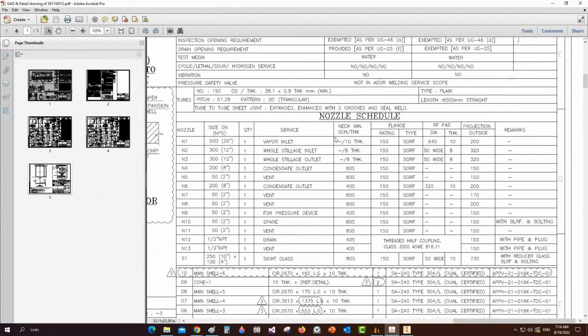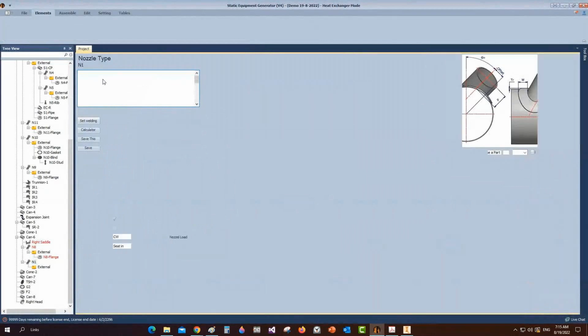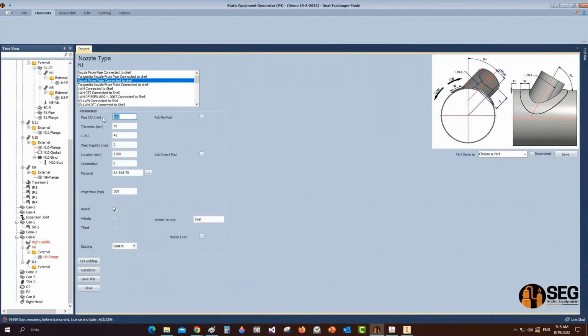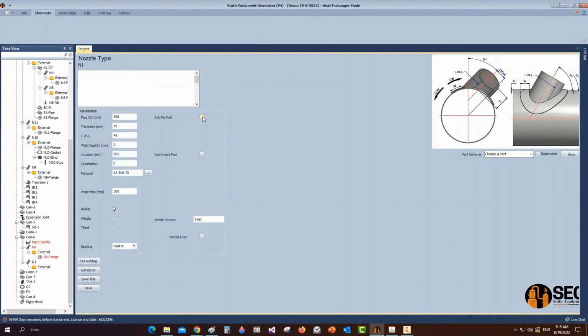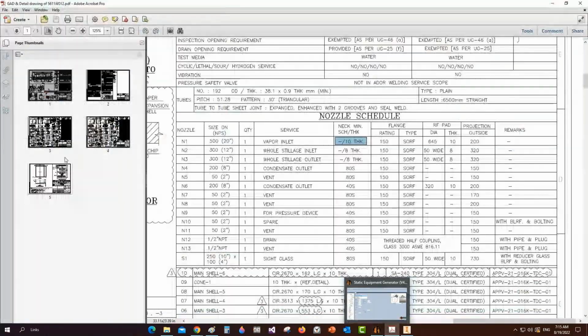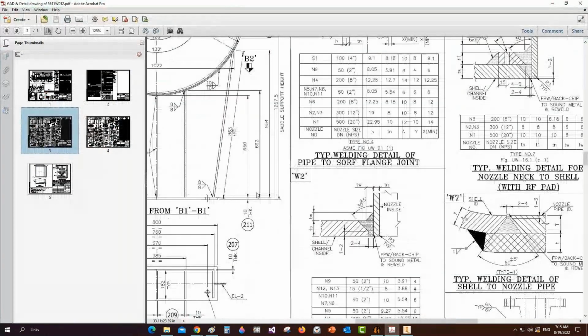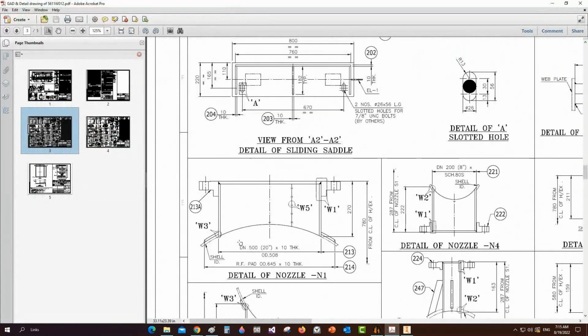So from here, let's select a nozzle from plate, not from pipe, sorry, and that's the outside diameter of 20 inches, 10 millimeters, the longitudinal welding line orientation here, the same location as the saddle, the orientation at 0 degree. We have a reinforcement pad. So if we check N1 here and calculate the outside diameter, it will be 75.